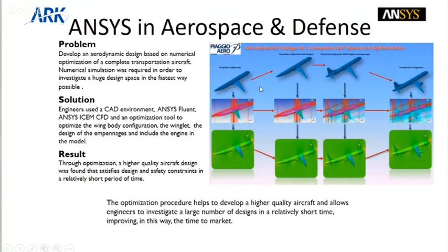When I started optimization, I did it on different aspects of the body configuration. I had a wing body configuration, a fuselage wing configuration, and then the whole assembly. To that configuration I first did the optimization and got an optimized structure. Once I got it, I assembled one winglet to it, and for the size and shape of the winglet we did the optimization.